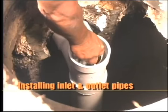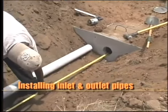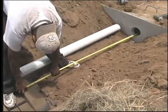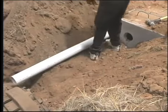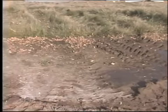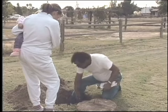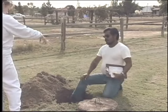When installing the inlet and outlet pipes, be careful to insert the pipe only 1 to 3 inches. If the pipe is inserted further, it may run into the baffle and plug the end of the pipe. This can greatly reduce the flow capacity of the tank and cause clogging and sewer backups. This error is usually noticed when or if the tank is inspected, but the problem is not always easy to correct at that time. The tank's inlet and outlet connections and seams must be sealed to protect against groundwater seepage